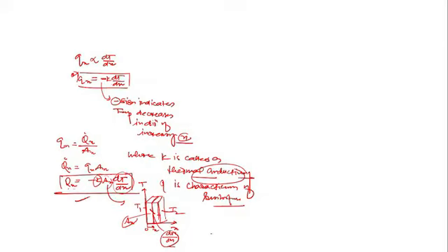So the meaning is that, my dear student, dT/dx is here, and the area at that point, normal to the direction of heat transfer, is Ax. Now if I change the material from steel to copper, what happens? Keeping the same dT/dx and same area, the temperature gradient is the same and the area is the same, but still the rate of heat transfer is different, just because the material has been changed.